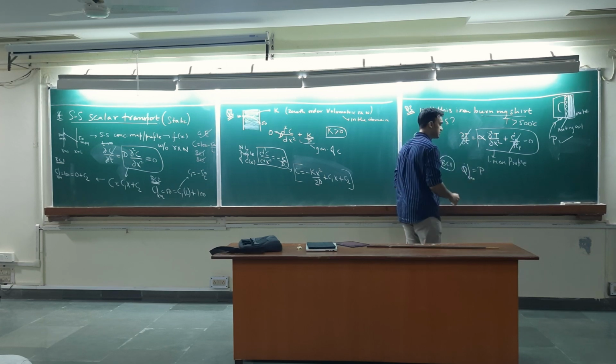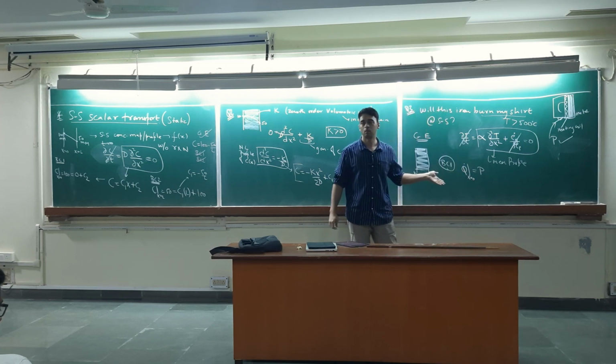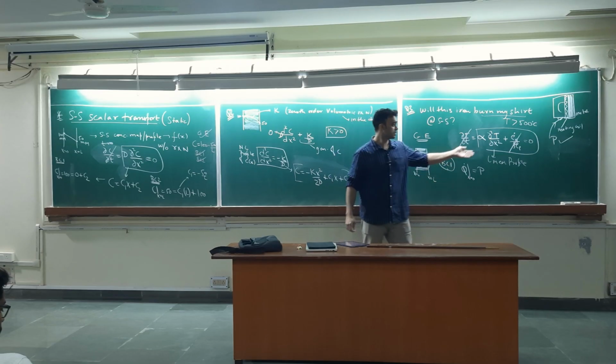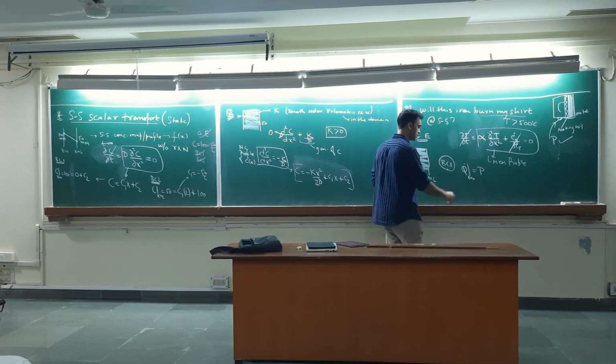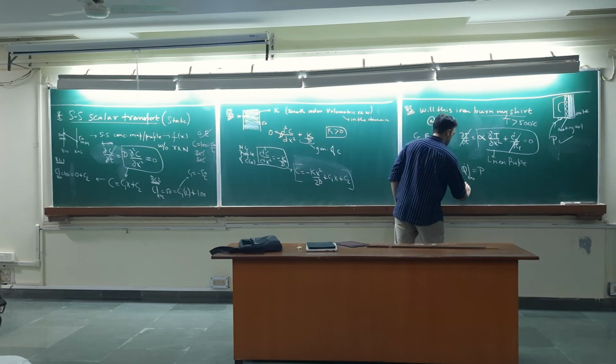This is P, but is this useful right now? How will you use it here? Everything is temperature. This is Q dot. So what do you need to do? Convert it using Fourier's law into temperature. What should I write then? Minus kA, right? It's not flux. dT by dx at x equals 0 is equal to some power.